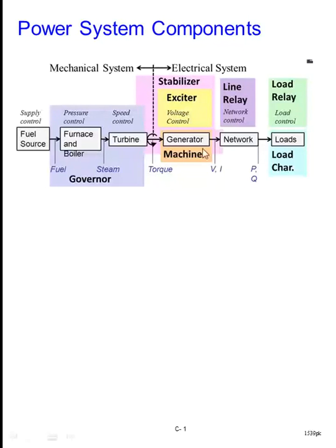This will include the synchronous machine, the synchronous generator. And on the machine you have an exciter to regulate the terminal voltage of the generator, and then to control the power, to damp out the power oscillations, there will also be a stabilizer in the AVR section of the excitation system. So we have the use of a stabilizer as a controller part.